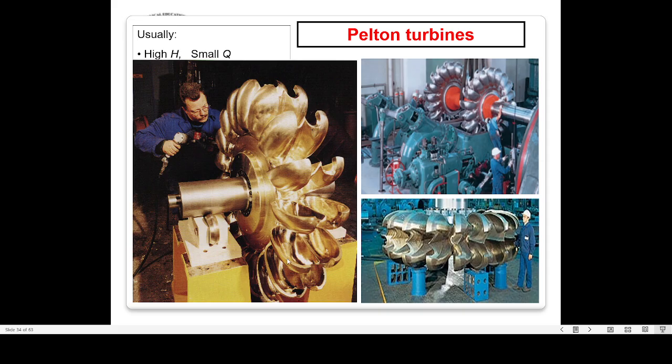Okay, so we can see here one of the arrangements, a pictorial representation for the Pelton wheel. So these are the blades. Okay, and we can see that they have a symmetrical shape, isn't it? And what we were talking about in the earlier description is nothing but the splitter. This is the splitter. So the jet will make an impact exactly at the splitter, and that will cause the jet to get deflected equally in either direction. Okay, this is the shaft of the turbine, which is mounted horizontally.